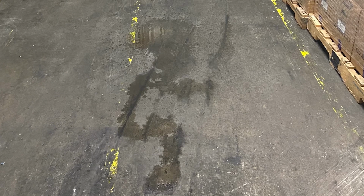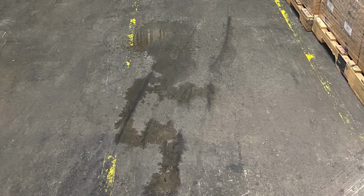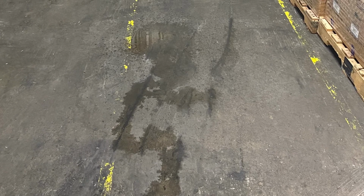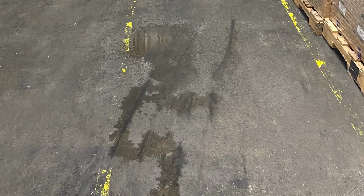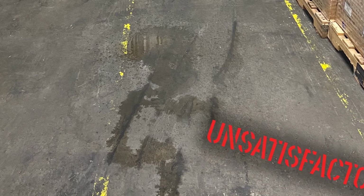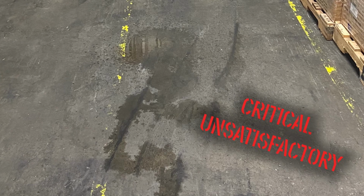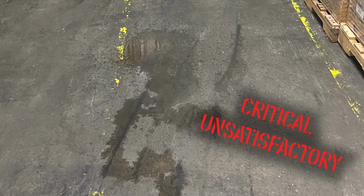This image shows a larger pool of water with obvious splash marks from an overhead drip. This area likely still has condensation or a malfunctioning drip line overhead and needs to be addressed. This is an unsatisfactory finding in a critical area and must be addressed before product may be stored in this area.